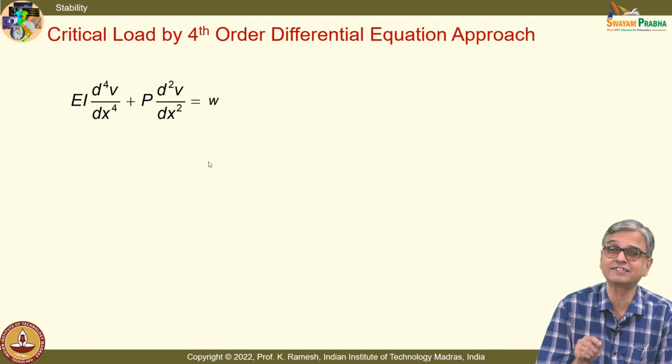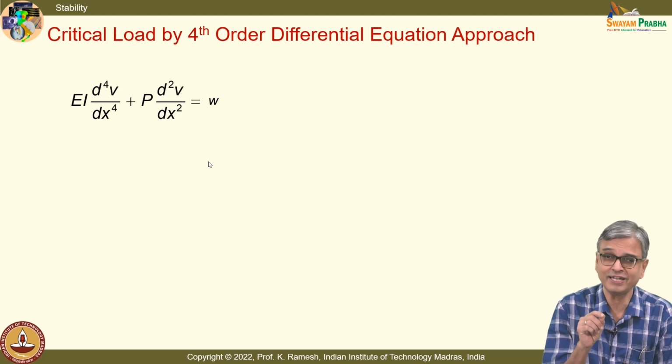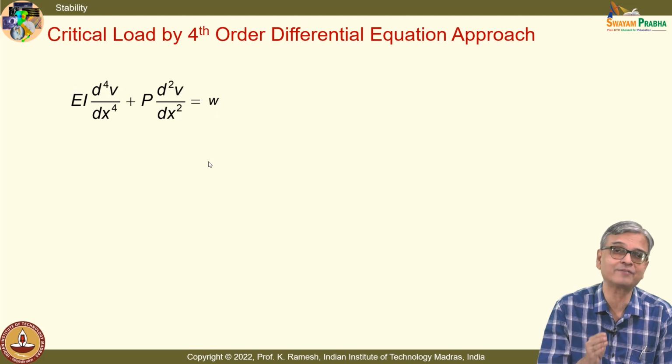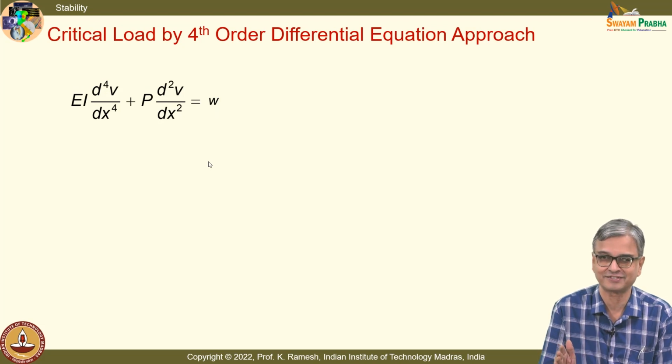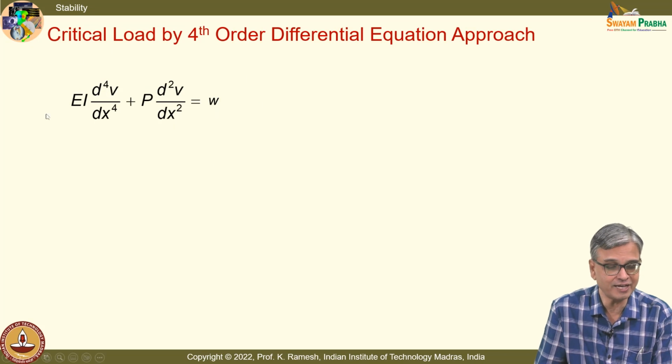What they are saying is, the moment curvature relation, we have linearized it. We have not taken that as non-linear. In fact, it is very surprising that when Lagrange and Euler analyzed, they had taken the non-linear expression and then did all the derivation. They have also indicated that. But here we have used only a linearized moment curvature relation. So, in that sense, it is an approximate expression.